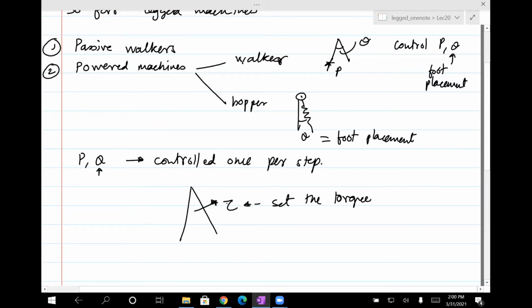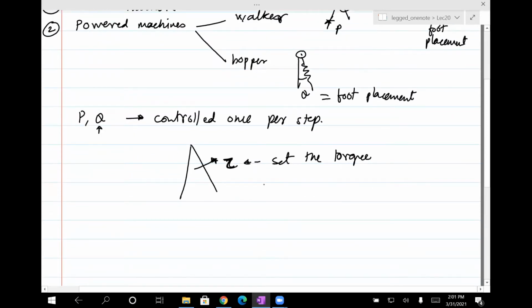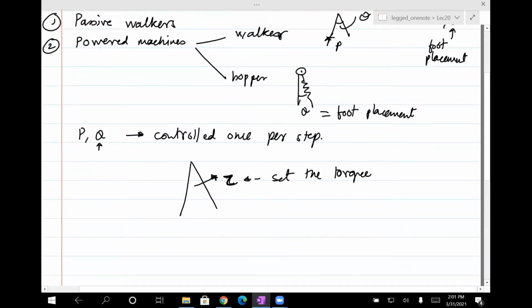But most of the time, our robots have some kind of motor which has either a voltage, a torque, or a current. Modeling a motor is a separate issue, but let's just assume that we have a pure torque source. That is, our motors can provide torques. They cannot give us thetas and p's. So those have to be computed by assigning the right torque. Our design problem is finding what torque profiles to put on the joint such that it will move the way we want.